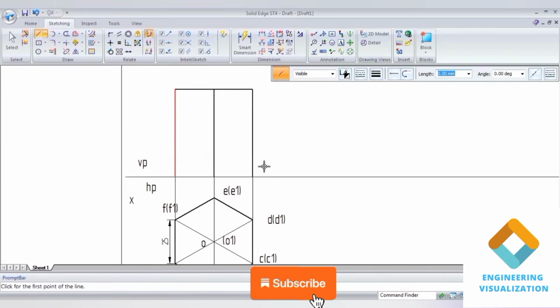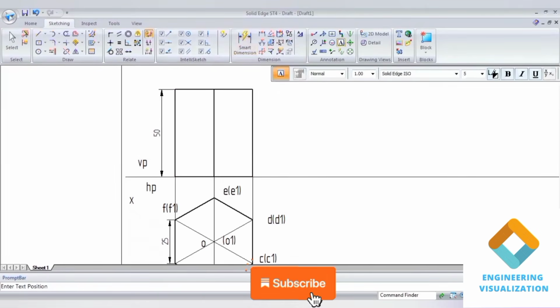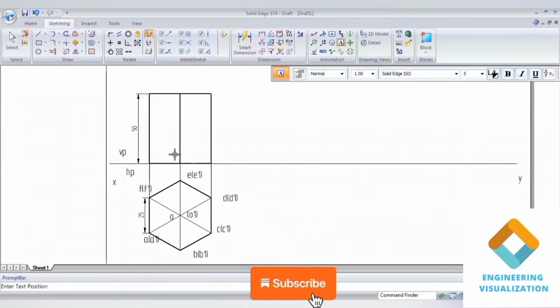Now write the front view notations, those which are visible from the front view. From the front view, a dash, b dash and c dash are visible, and d dash, e dash and f dash are not visible. Not visible means we should write them within brackets. In the same way we write the same for the bottom face also.